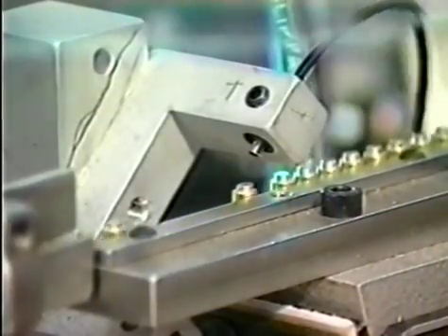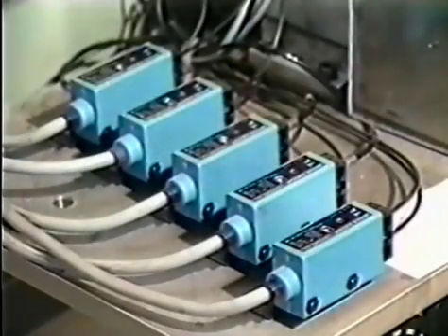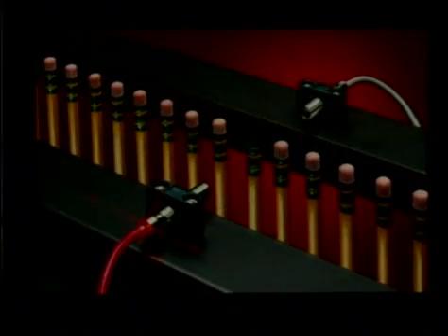Fiber optic photoelectric switches are also available using the same type of scan techniques. Fiber optics, though, offer advantages because they can be placed in very tight spaces where detection is required, while its switch base assembly can be mounted elsewhere. In this type of switch, the receiver and emitter controls are located in the same enclosure, with the fiber optic cables, either one or two, going to the detection area.